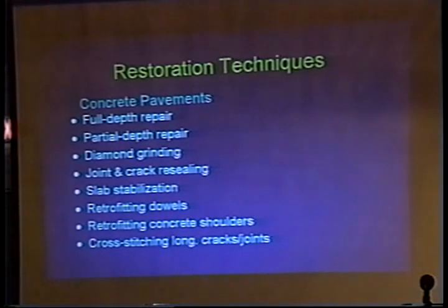Retrofitting concrete shoulders. I think ODOT has had some questionable success with that. I think a lot of it is due to the selection of the concrete pavements, where the pavements they chose were old to begin with. To go in there and retrofit with new concrete tied to the existing concrete, you probably didn't get a good payoff. The other thing is, this might work in a concrete pavement where you realize after the fact that maybe we should have had shoulders on there.